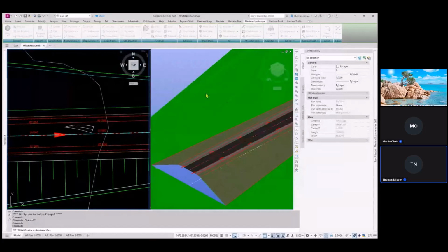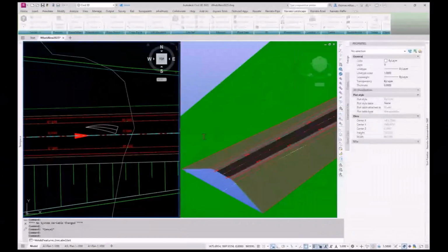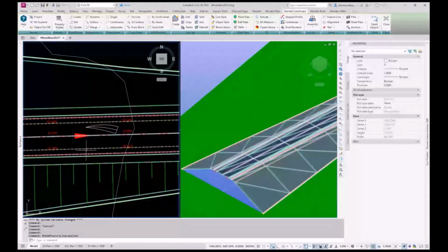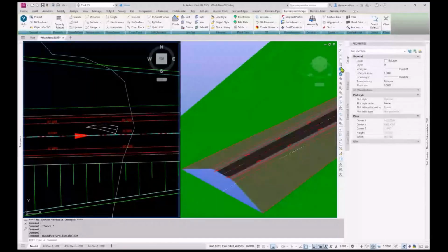here. And this one allows me to select the specific frequency or interval, and that's what happened here. Even though the corridor was calculated in a more dense frequency, it's only displaying the labels every 20 meters. But you can only insert labels at a calculated vertex on the feature line.